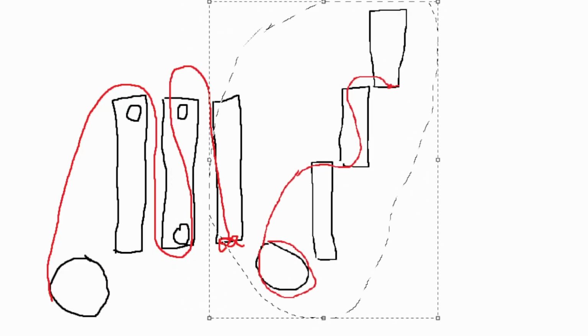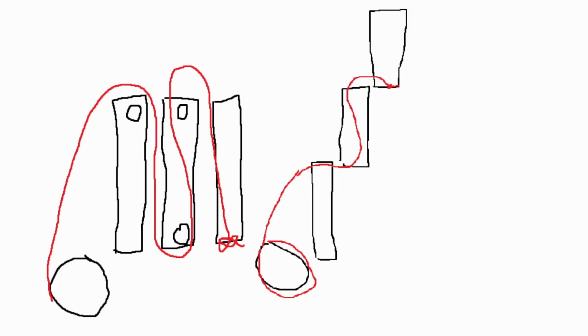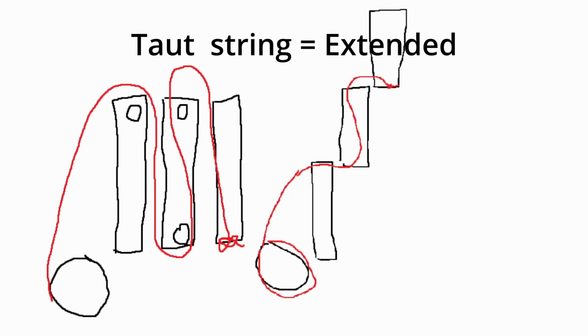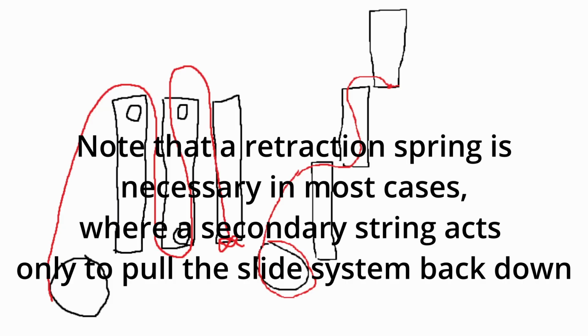If we drag over though, we have this as our fully extended stage. Okay, so this is once the pulley wraps up, it tightens the string to its tightest possible configuration. So this one takes as much room as possible, the one on the left, but the one on the right uses as little string as possible, with the rest being wrapped up in the spool. So it goes over the first one, and then it's much easier for the string to be right next to the top of the first slide, as that's a much shorter path than going from the top of the first slide to the bottom of the second. So that way, those two slides are right next to each other practically. And then it goes up, and then it pulls the bottom of the third slide up to the top of the second, as you can see here.